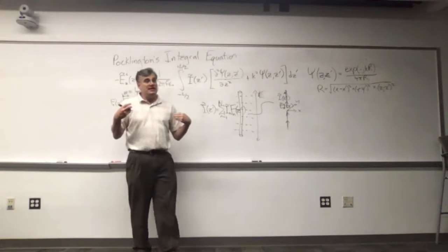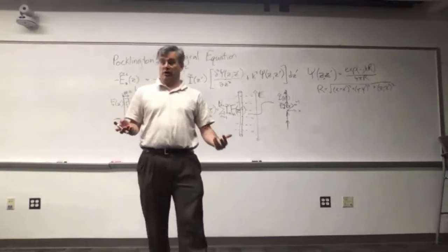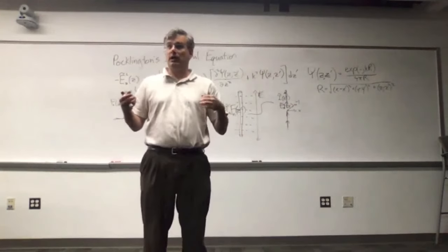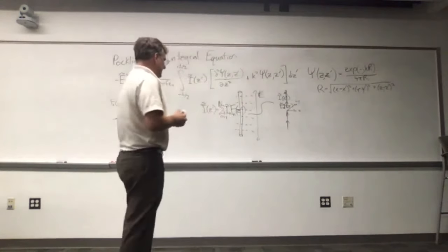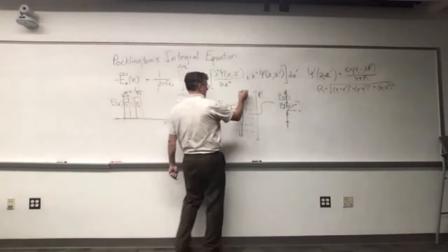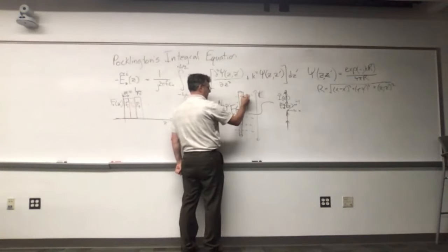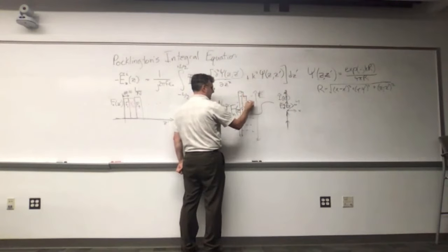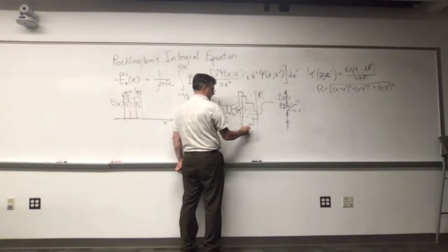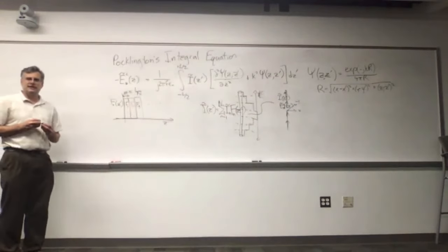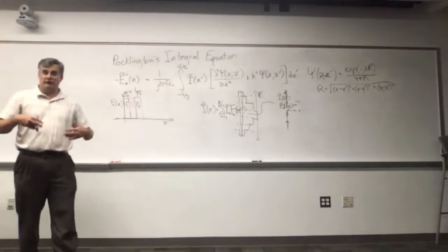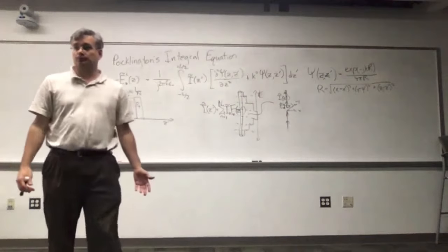So there's going to be a discretization error in our analysis because we've introduced a function with finite samples, right? What we're really saying is that the current that I'm going to model here is probably going to have some sort of stair-step shape when I add all this up, right? It's going to be something like that. And you know what? That's okay. That's part of your discretization error.